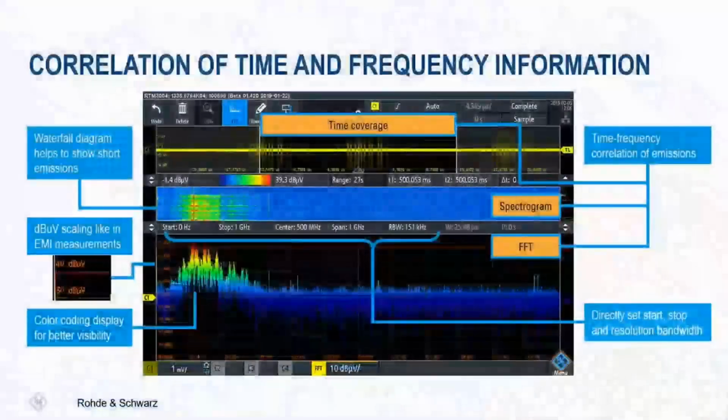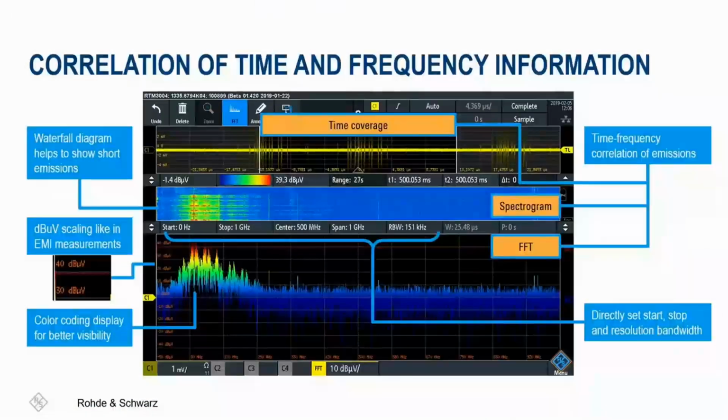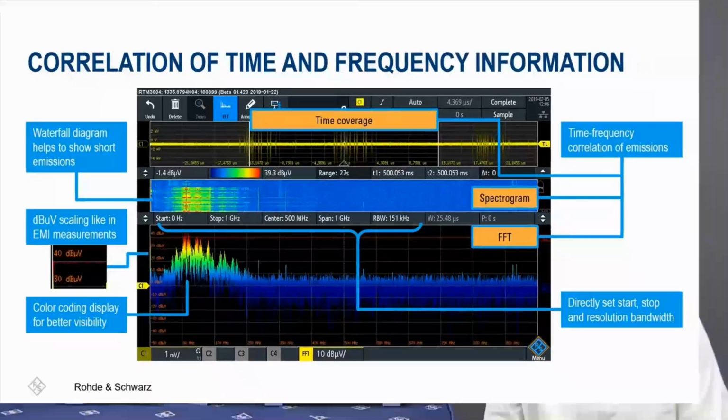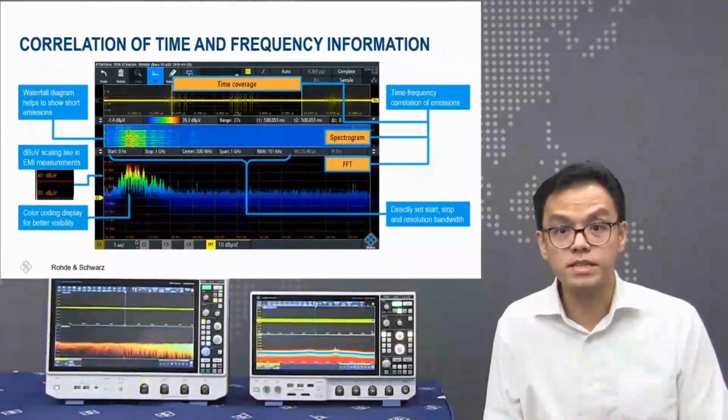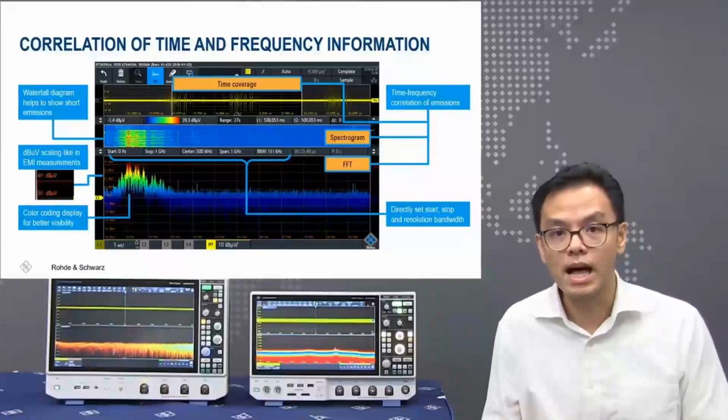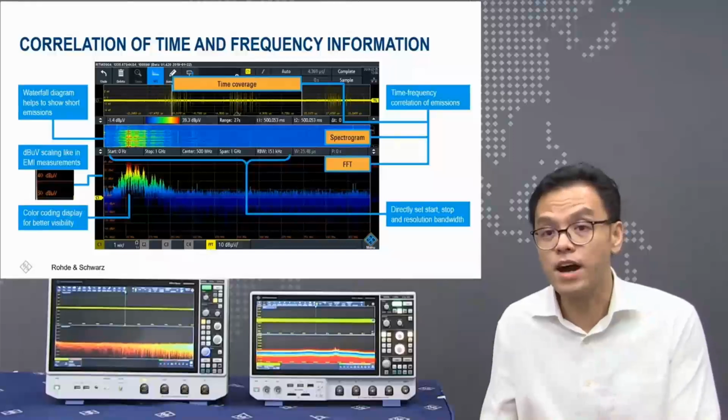This provides us valuable insights into the behavior of the device under test. While an oscilloscope may introduce some noise, it's not as critical in a debugging context as compared to a compliance setting. As engineers, having visibility into noise characteristics allows us to quickly experiment with trial and error to identify possible fixes.